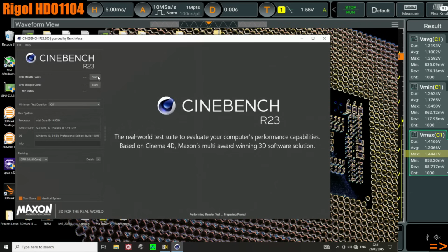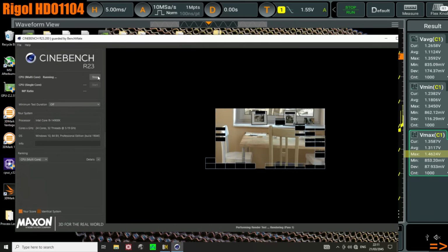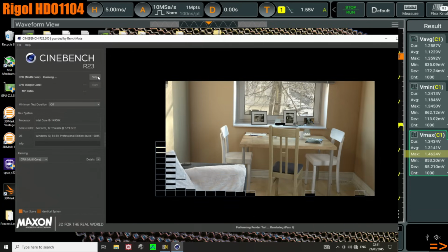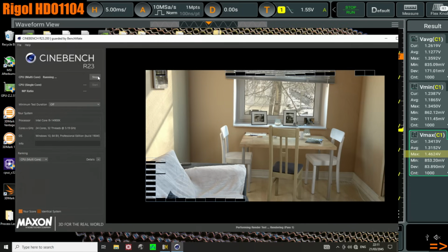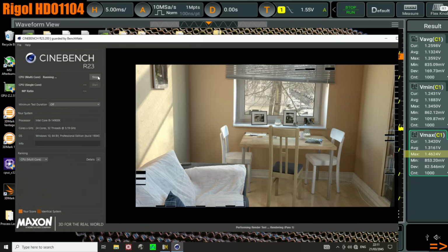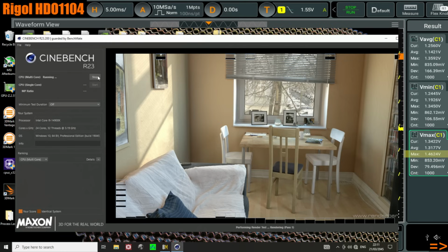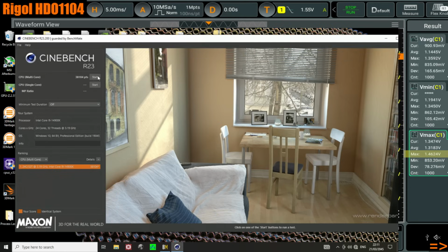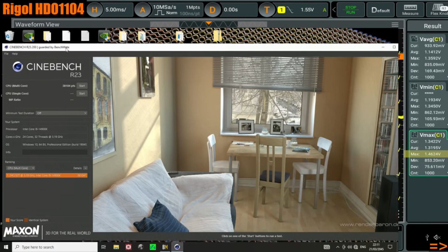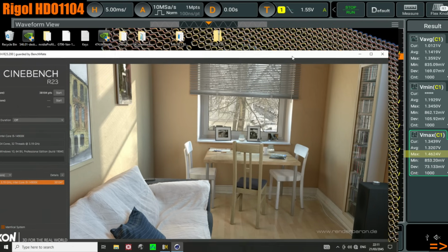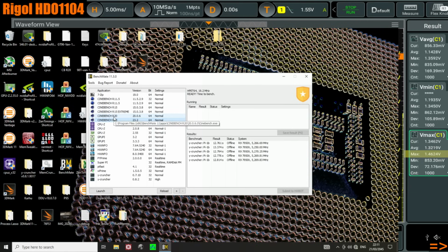Okay, it's actually not worse, because the silicon quality is higher, but because Intel's pushing the frequency so high out of the box, the vid tables end up really high anyway. Right, whereas the very worst i7s are slightly over 1.4, whereas the average i9 is around 1.45. Anyway, like I said, lowering the all-core ratio doesn't really affect Cinebench R23 unless you had a CPU that wasn't constantly power throttling, which I don't think is possible with the Intel defaults.